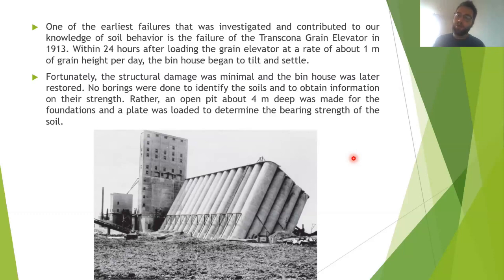There are parameters you need to define, and that parameter is the speed of accelerating waves in the ground. That's the parameter that you pass to the structural engineers, and they make their structures based on what you said there.